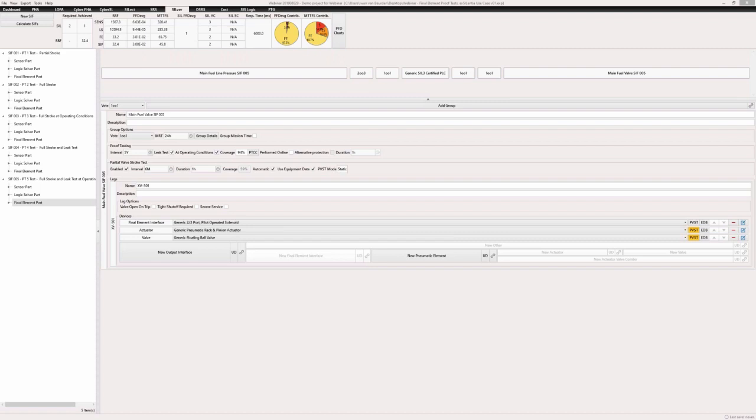It all depends on philosophy. Some customers want to do an end-to-end test, and most of the time that end-to-end test is then also looking at, let's say, the application logic. And some customers want to basically test the entire application logic every proof test. You could argue, however, that the objective of a proof test is to detect dangerous and undetected failures. And the change of the application program, which is then basically being looked for, is really a systematic issue.